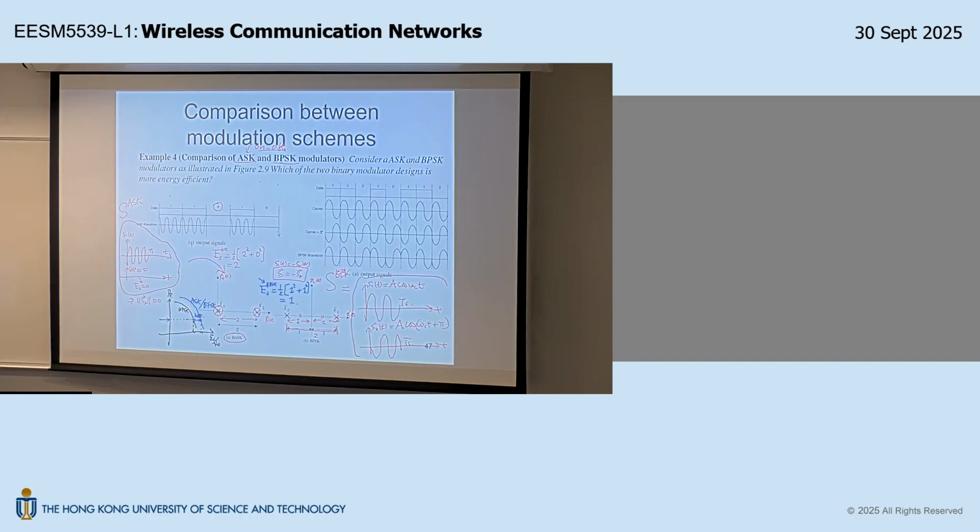using the same family of modulation, this is called APSK. You have 8 points. So this APSK means the 8 points are equally spaced on the circle, meaning that each of these points have equal energy, okay? Because they are on the circumference of a circle. Now you compare QPSK with APSK. So what is now this time, let's say we equalize the energy.